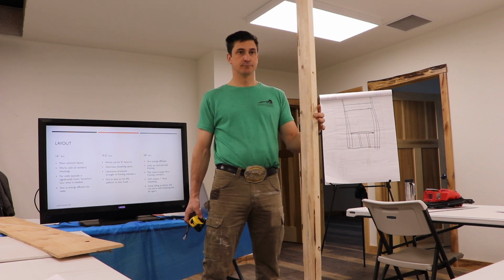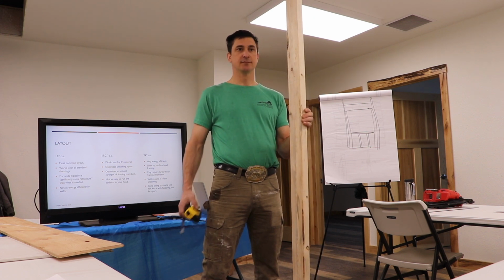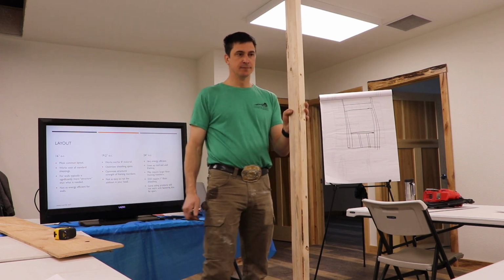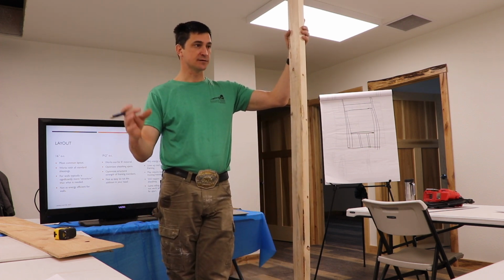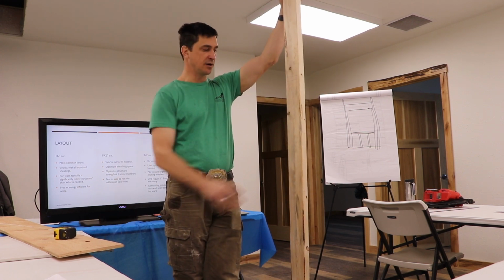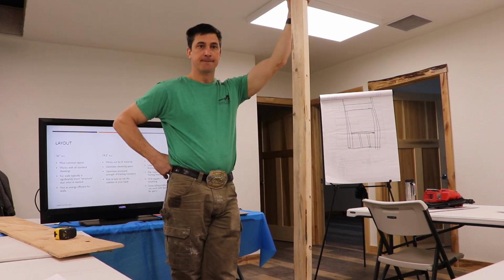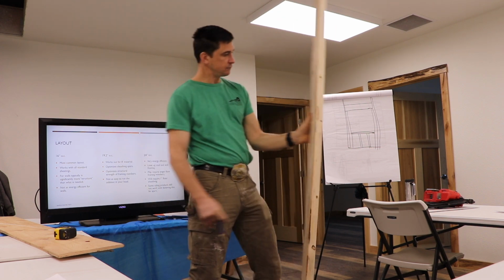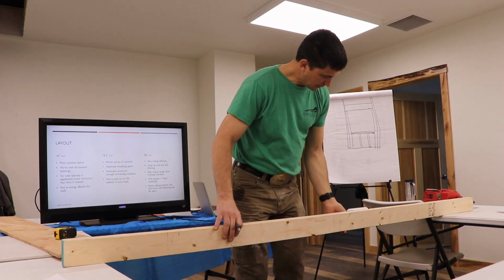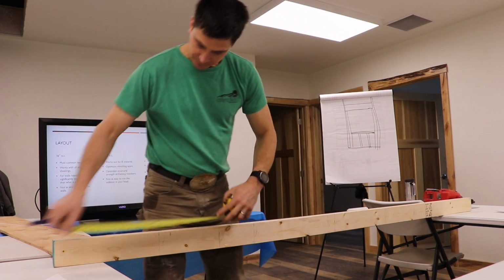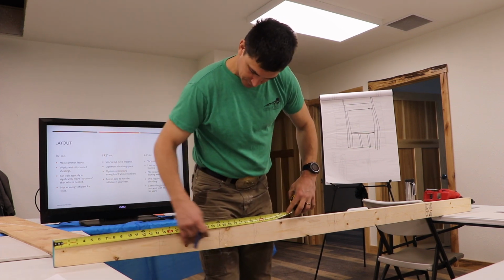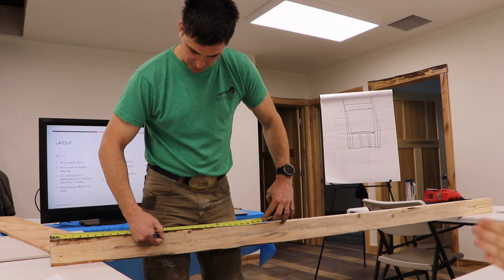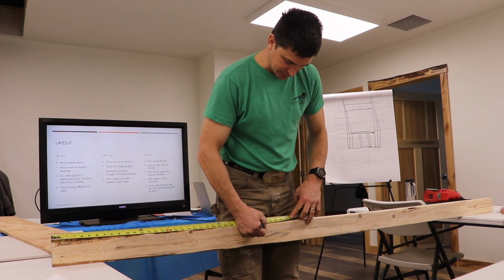Like 4. No, way off. Like 2? 1. Okay, it's like 1.1 per inch of thickness. So what's the R value of this 2x4? 3.5. Okay, 3.4. If I lay out my wall, let's flip it over so that we have less marks here to deal with. Okay, so I can lay out here, got my 16 on center.